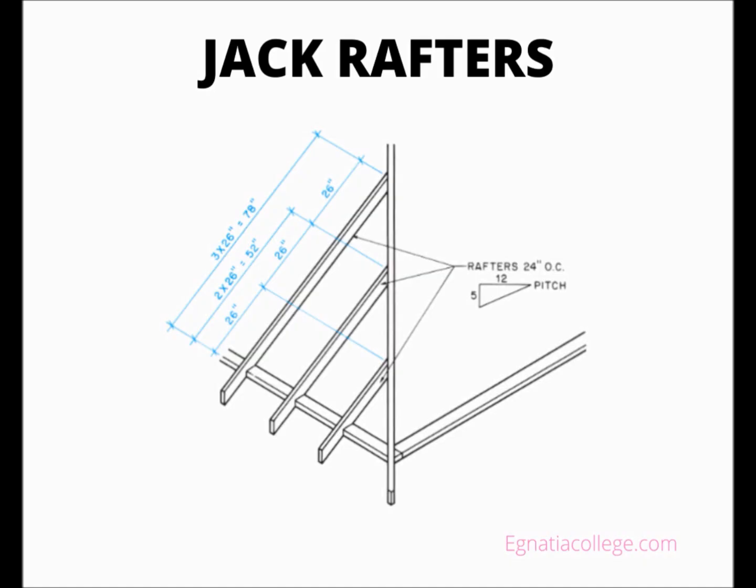The amount of this variance depends on the spacing of the rafters and the pitch of the roof. The third line of the rafter table is used when the rafters are spaced 16 inches OC. The fourth line is used when they are spaced 24 inches OC. As with the other lines of the rafter table, the inch numerals at the top of the square are used to indicate the unit rise of the roof. For example, if a roof has a 6 in 12 slope and the roof framing is 16 inches OC, the difference in the length of jack rafters is 17 and 7/8 inches.